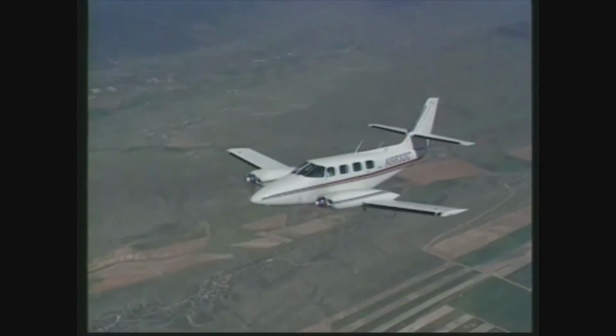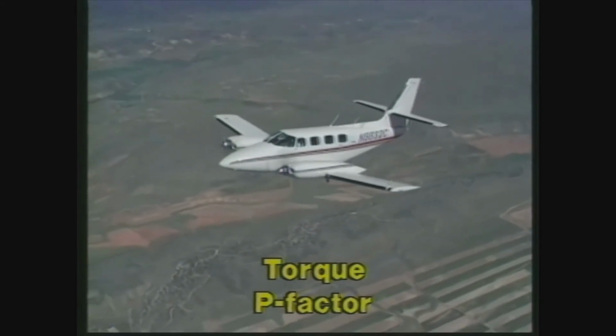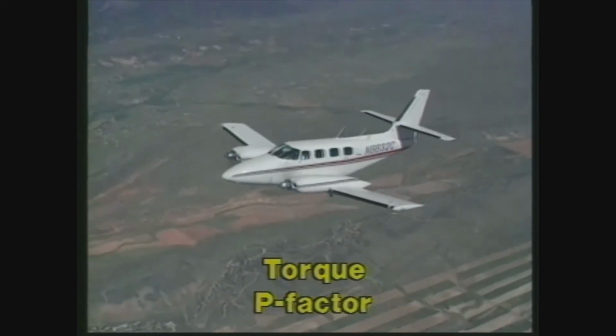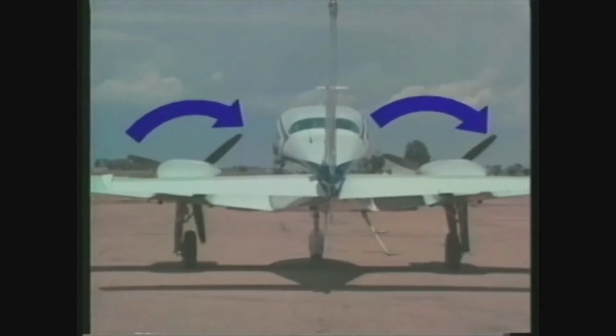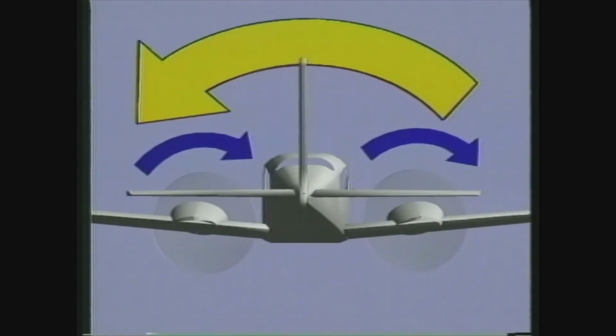Two familiar aerodynamic terms, torque and P-factor, warrant special consideration for multi-engine flight. On some twin-engine aircraft, both propellers rotate clockwise when viewed from behind. This type of aircraft is often referred to as a conventional twin. With this type of aircraft, the torque produced by both propellers rotating in the same direction causes a greater rolling tendency to the left than in a single-engine airplane.